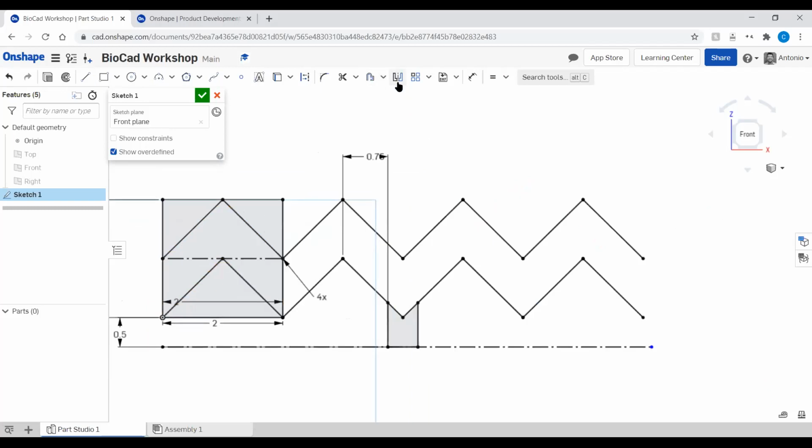So it looks like two lines mirrored over a vertical line. So you click the mirror function there. First, it asks you to select a mirror line. So what we're going to do is select this horizontal line that's running directly through the middle of our quarter mesh right here. So I'm going to select that line.